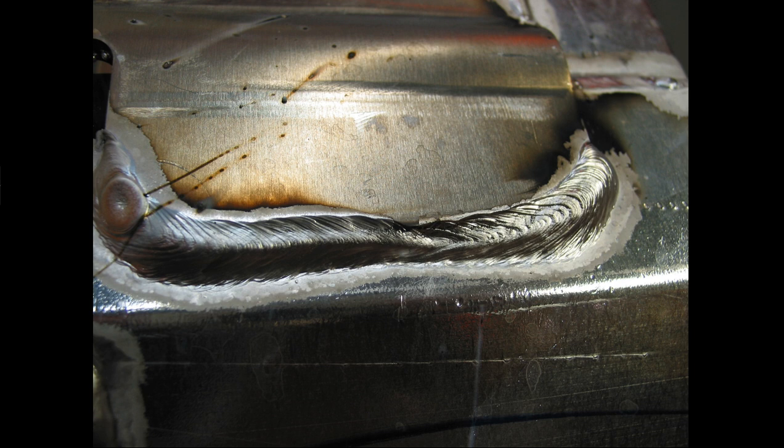Now, this is clearly a deficient weld. There's no need to dwell on it too long. But this one is really nice, and I wanted to point it out because you don't always have to grab, especially if it's a reprocess, you don't always have to grab brushes and cleaning and everything else before you get started. With the AC process, you could just dive right into this and start a little bit of a TIG weld right there and weld across there, and you don't really have to do anything.